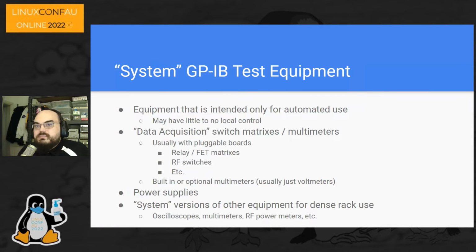There are system power supplies. The wonderful old HP system power supplies are great if you need lots of power, either lots of current at low voltage or high voltage. Their UI is not great, but they implement a lot of stuff on the GPIB interface, and you can control them that way. The other thing is they're often really cheap because the UI is not great, and if you're buying them used, you're probably wanting to use it yourself.